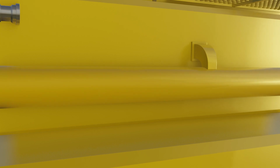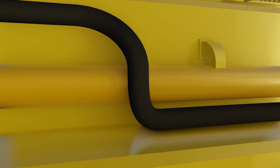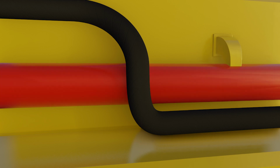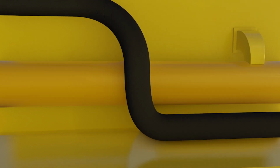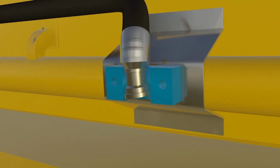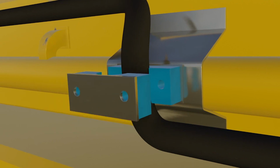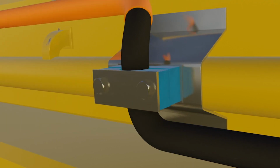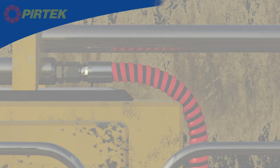In this situation, there is a hose passing over a hot manifold. We feel that this is wrong. Why is this wrong, and how can we correct this? The heat from the manifold is going to adversely affect the hose. The hose is going to lose its flexibility and it will burst. We could isolate the hose with the use of a shield. Additionally, we could also use a heat sleeve to protect the hose. Clamping the hose in place in this instance would also be best practice.